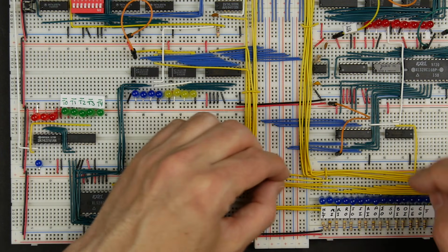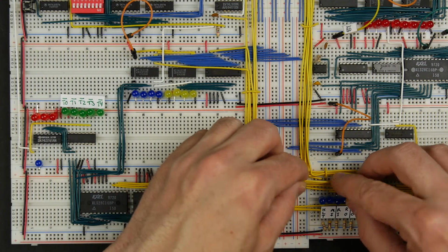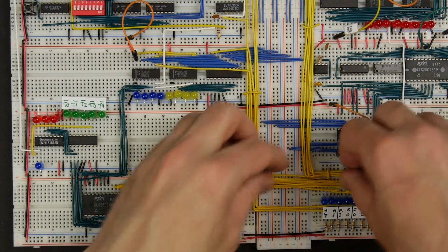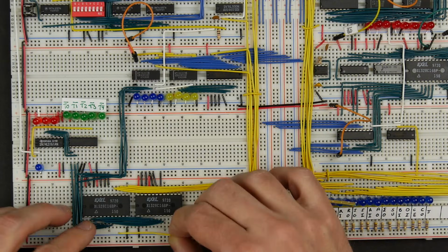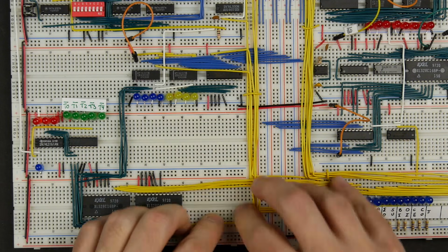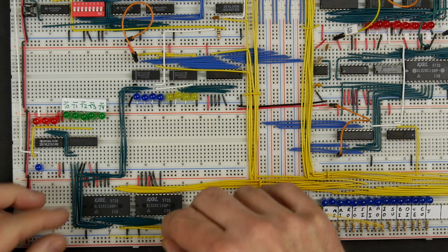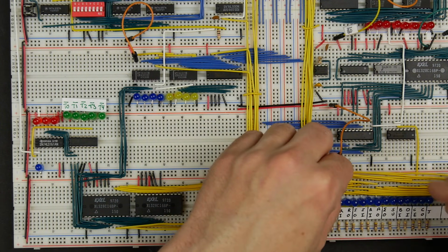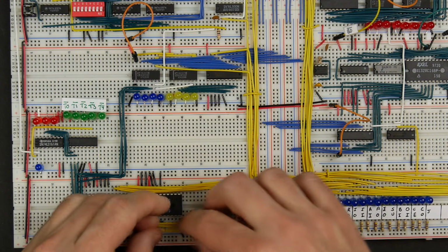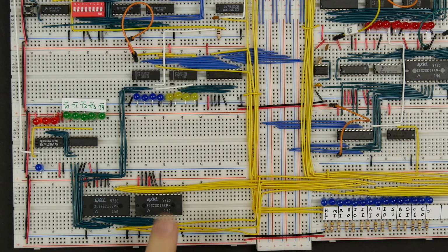So I/O 6 is going to connect to the next signal, which is memory in. I/O 5 is going to go to RAM in. I/O 4 is going to RAM out. And I/O 3 is going to instruction register out. And then I/O 2 is down here next to ground, and that's going over to instruction register in. I/O 1 is going to A register in. And finally I/O 0 is going to A register out. And so that's the first 8 of those control signals hooked up to the 8 bits from the first EEPROM. And so now I'll just do the same thing for the second EEPROM.